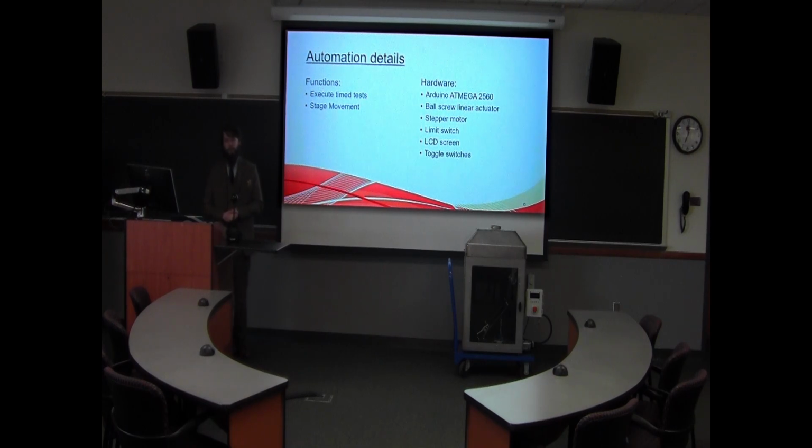The Arduino and stepper motor can move the ball screw back and forth, and the limit switch tells it when it is at the home position so it knows where it's at in the travel back and forth. To interact with this system, we have integrated an LCD display and a toggle switch system to be able to select your testing. You can flip the toggle switch, and the LCD screen will say what test you have selected. It will move the burner or start a digital timer to count off how many seconds have passed. Then it can move the burner back to its original position.